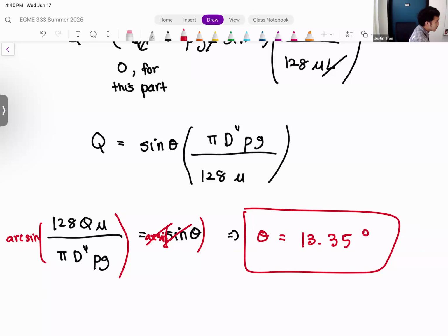Okay, good. All right, so that was a good warm up, right? So laminar flow, very nice to work with because we have these explicit formulas. In fact, the Hagen-Poiseuille formula for the most part gives us everything we would ever need for pipe flow. It basically gives us a way to relate pressure drop and flow rate and the diameter.